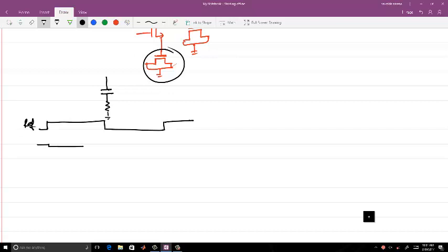It will be very small. So this is reference 0, and I have an I leak of some delta value all throughout. That will be the leakage due to active devices. So what will be the response of the PLL due to this?